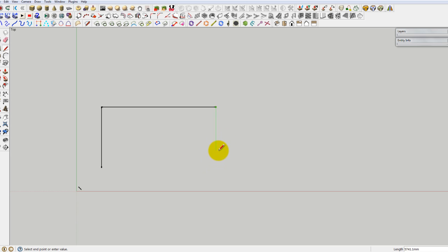But instead of entering the value again and again, what we do is we snap to this point without clicking anything for 3-4 seconds, and then you bring it like this, and you can see that it is being snapped, and it's getting the point of imaginary intersection, right? So you can just click on this one and join it.